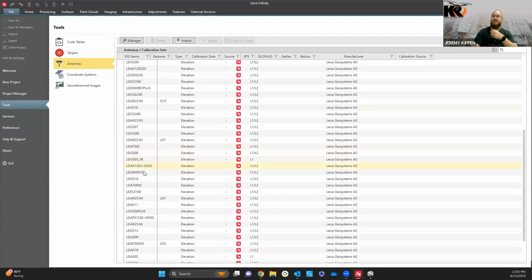We've got the Leica GS18 right here. If I was doing a static observation, where you observe a point for more than 2 hours, up to 24, 48 hours if you wish, you then post-process it, because as it's collecting the satellites, you will be able to post-process it and receive a corrected position. That can be for a later Lunch and Learn as well.